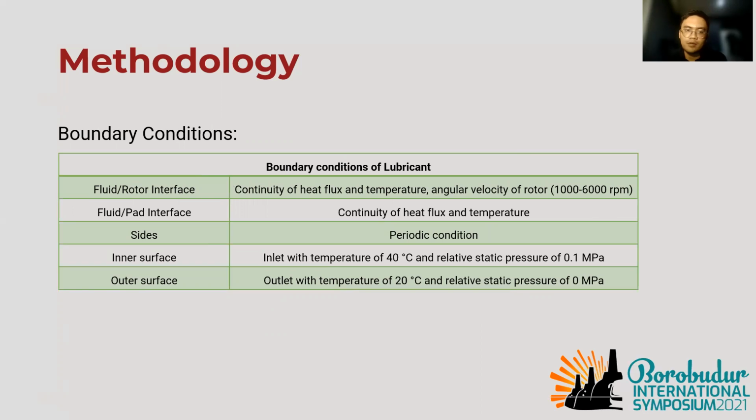And these are the boundary conditions. The top surface is the fluid-rotor interface, a continuity of heat flux and temperature with angular velocity of rotor 1000 to 6000 RPM. The bottom side is the fluid-bed interface, continuity of heat flux and temperature. The left and right sides are called sides with periodic condition. The inner surface is the inlet and the outer surface is the outlet.